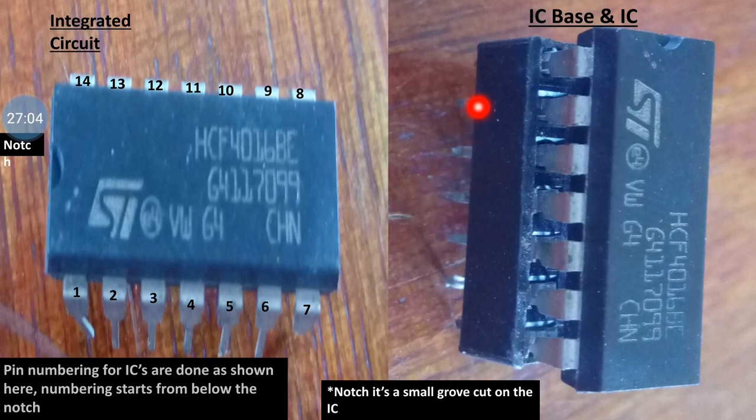Here you can see an IC base. The IC base is used to protect the IC from getting damaged. When an IC is directly soldered in an electronic circuit, there is a chance that the IC may get damaged due to overheating.